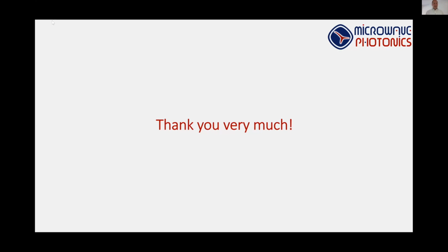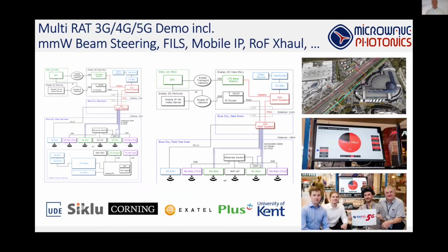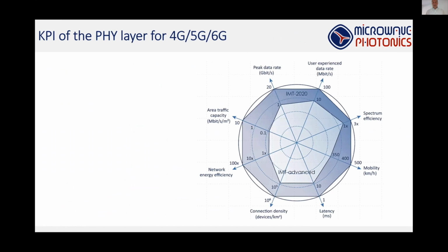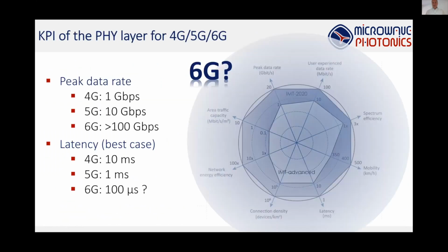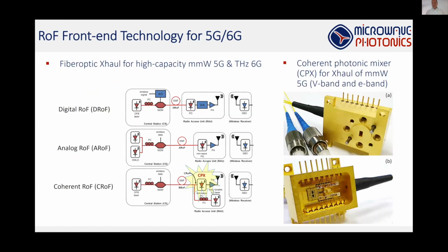Yes. Okay, so no, we are using direct optical to RF conversion in these cases. There is electronics included, let's say for amplifiers and these kind of things. So if I show you one example here, basically this device here, if we try to look into more details, I try to enhance that here. So basically what you have here is two fibers coming in, and then we have a balanced photodiode here. And then there is an amplifier between the balanced photodiode and the antenna.